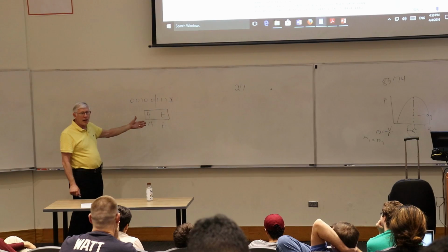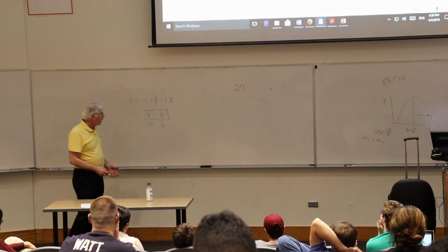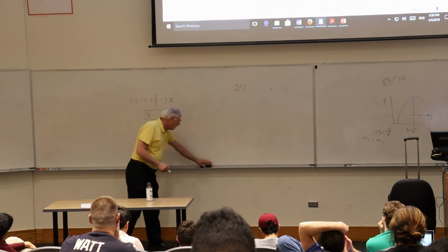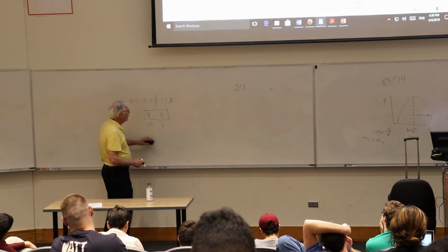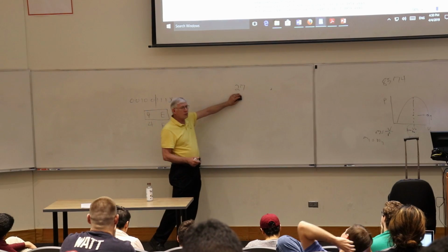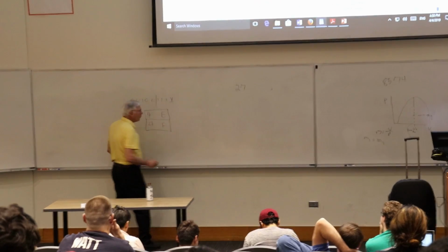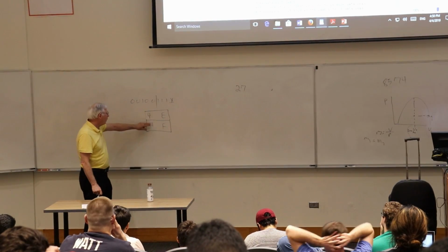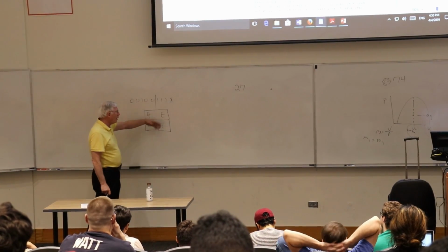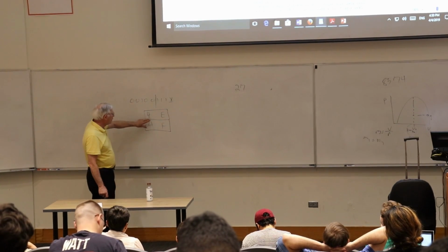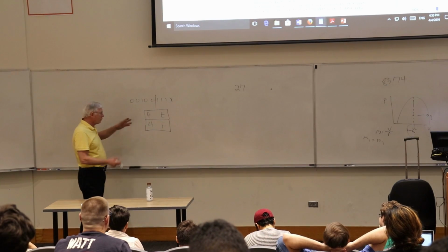Or is that supposed to be the actual address, or what the hell's going on? And you don't really know. It can be very hard to figure out. So in this case, the 27 is the unshifted 7-bit address. There are actually 2 addresses for this part, 4E and 4F. 4E would be the write address and 4F would be the read address, or maybe vice versa. I get confused about that too. But in any event, it's confusing.